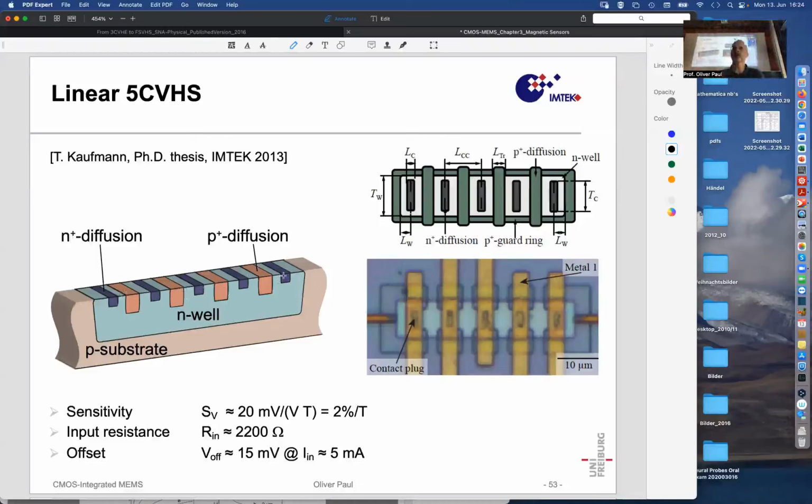in order for this effect to manifest itself in a Hall voltage. And then also we would benefit from the slightly lower doping occurring in the depth of an N well. The doping of an N well decreases as you get deeper and deeper, and at some point it is so low that it is actually no longer compensating the P substrate, and that's where it transits from N to P, where you have the PN junction.